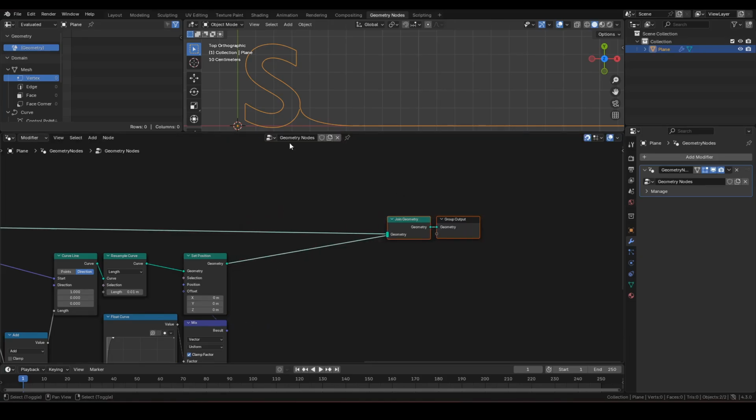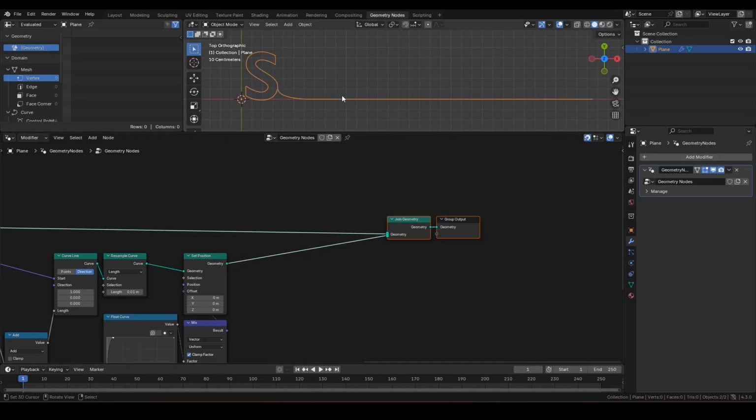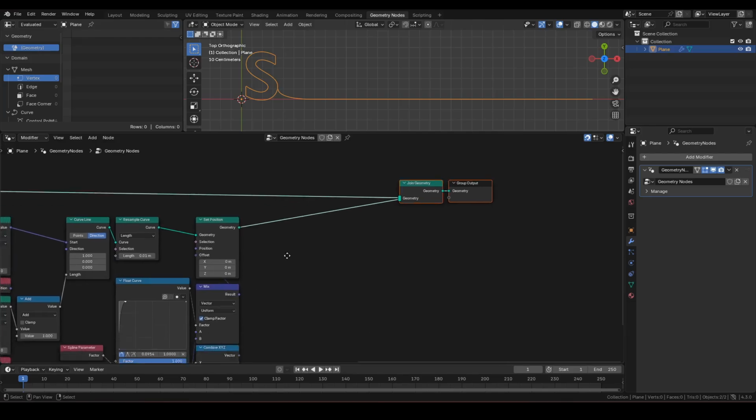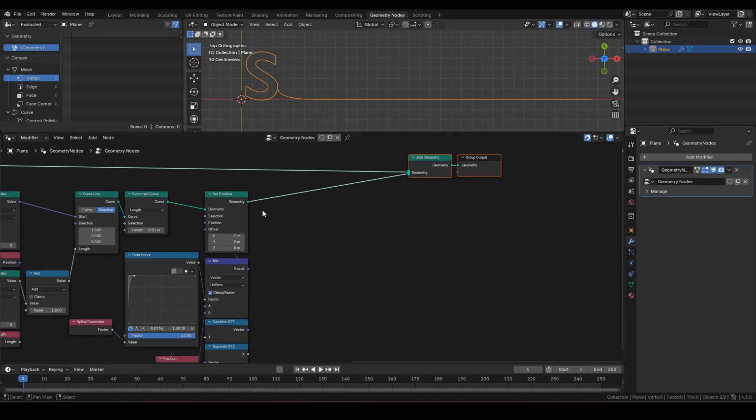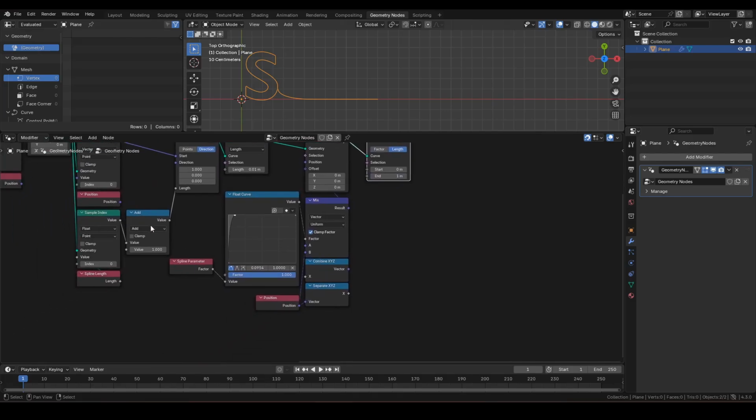But before we move on, this guide spline has become a little bit longer since I've made it slack down. So what I'm going to do is use a trim curve to trim it back to original length, which is going to be this value right here.